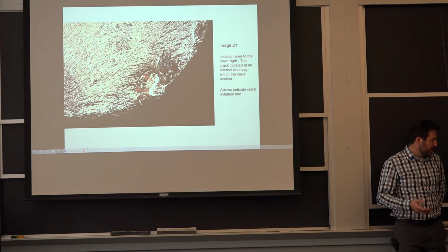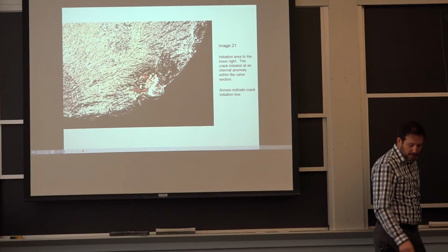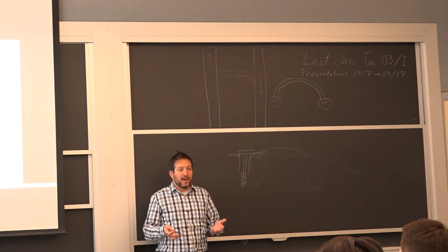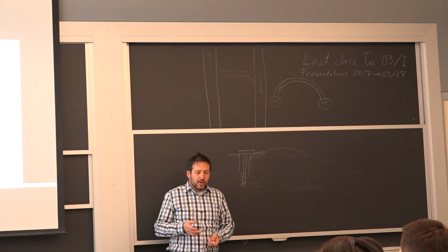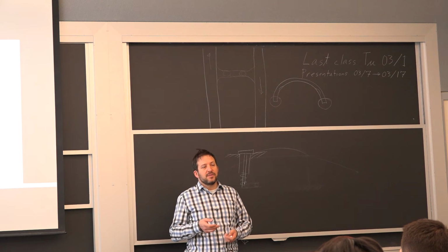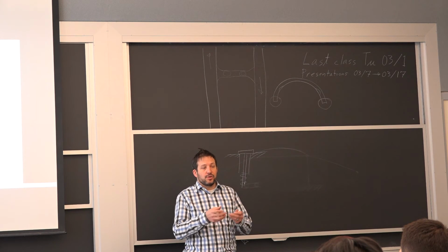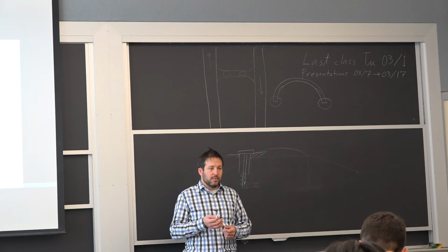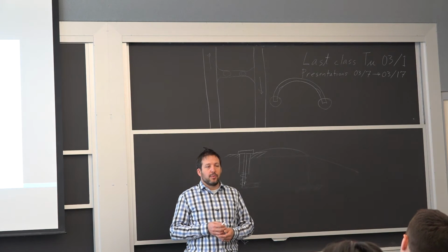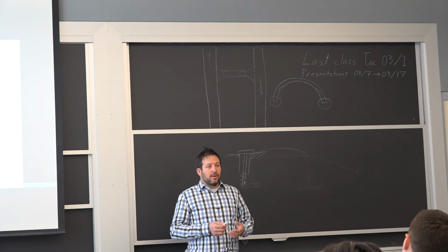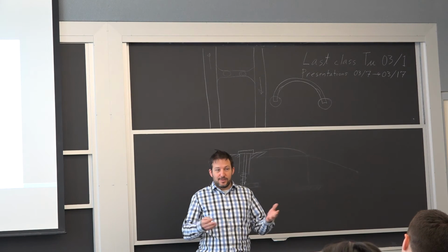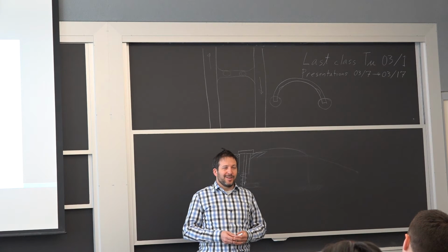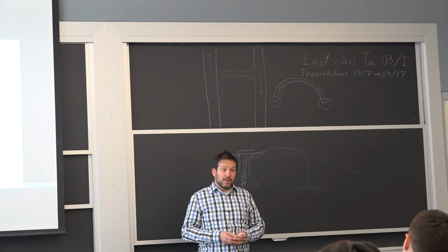If you're trying to determine the strength property of the material itself and you have a clean piece, it will matter a lot. For a practical application, a lot of times you have something additional to just the surface roughness that's affecting the crack initiation. Whether it was a little bit of a wear line, or a large inclusion, or a weld that is just a pure stress riser, the toe of the weld. So a lot of times it doesn't matter.